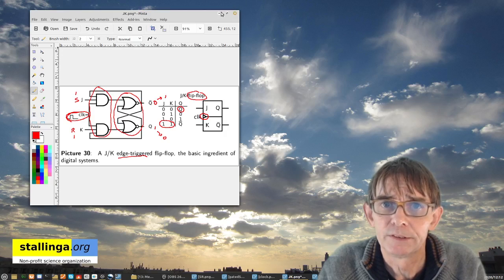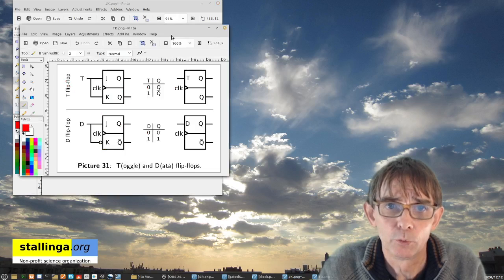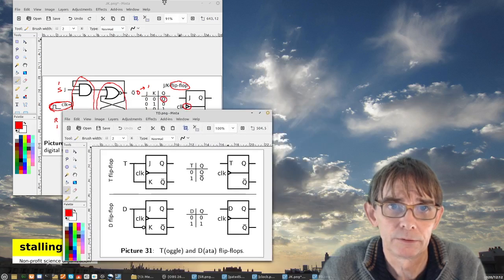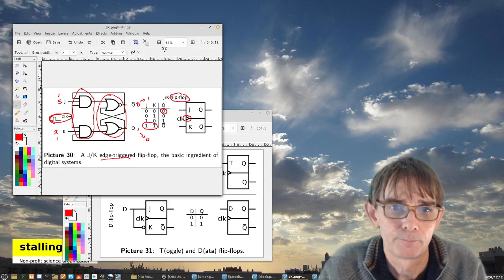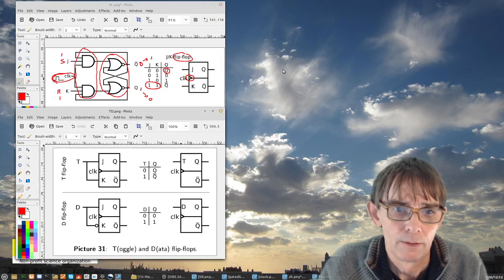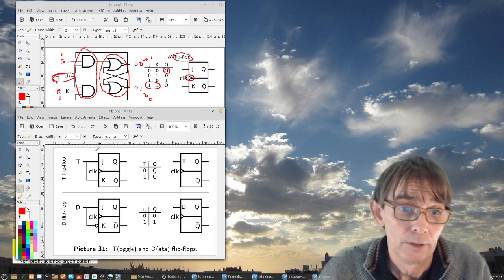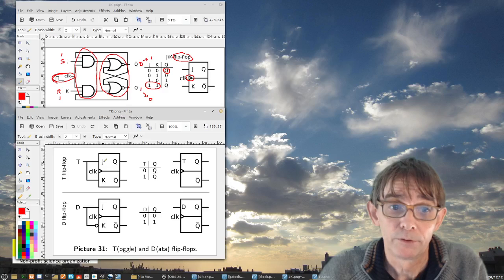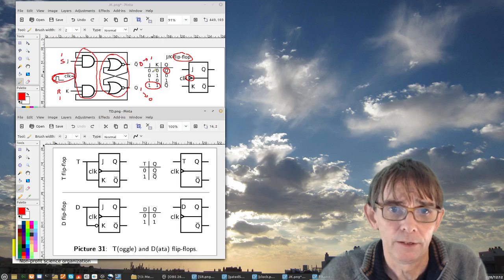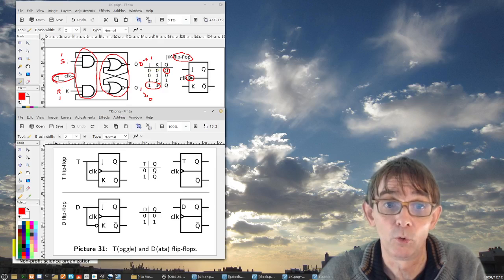Now finally, to finish this lecture, this flip-flop we can actually use in two ways to form simpler flip-flops. So if I take this JK edge triggered flip-flop and apply a signal with J and K equal, actually I exclude these two possibilities where J and K are different, so I can only apply 0, 0 or 1, 1.